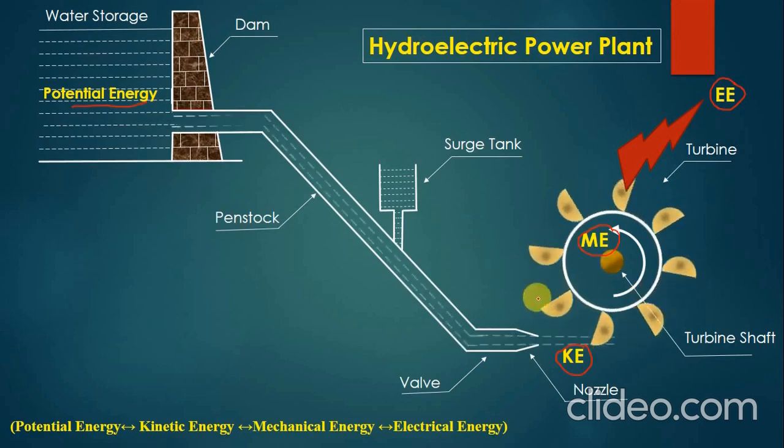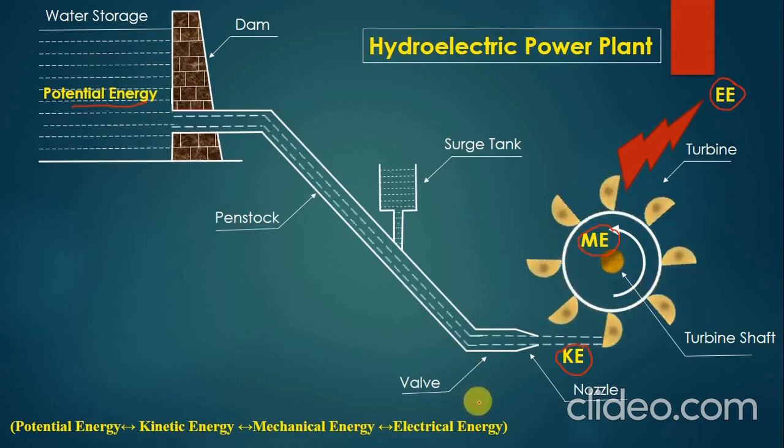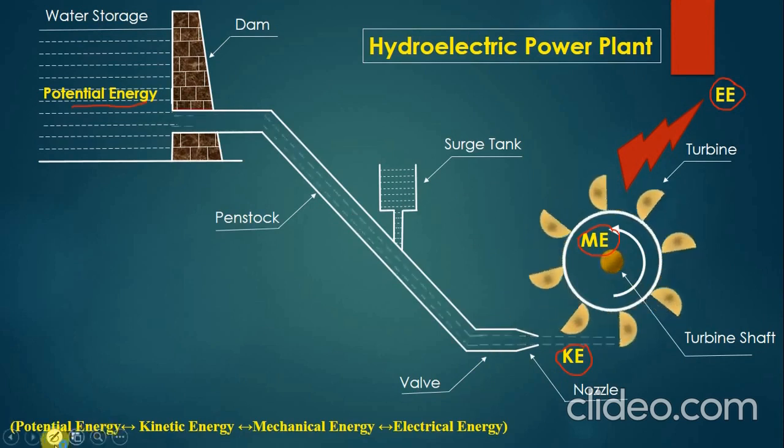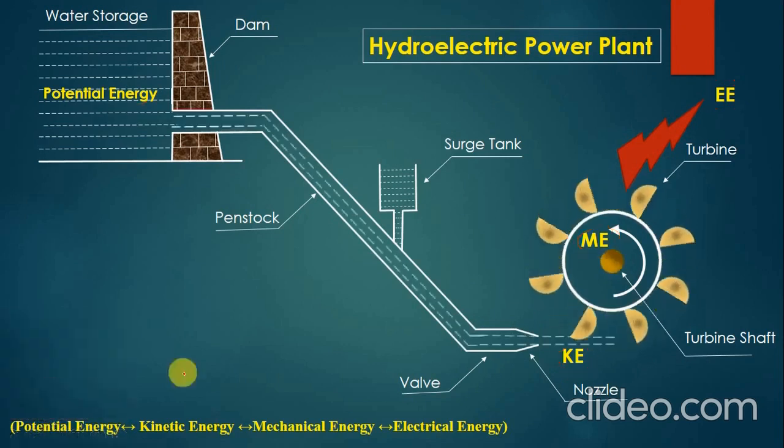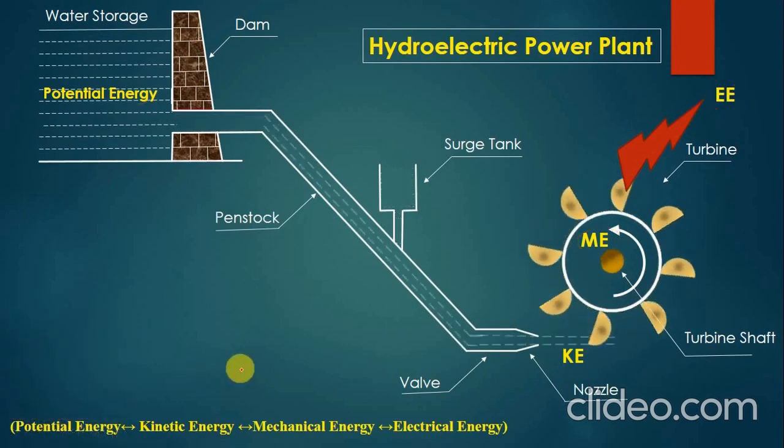Now after this, when we have to stop this turbine, what we have to do is close the valve which was present here. So after closing this valve, what happens, let's check. When we close it, let's consider that I have put a valve here, means now it is closed, and the flow of the water has also stopped. When we suddenly close this valve, the water which is rushing through a 10-foot diameter pipe will give a very high pressure on this particular area.